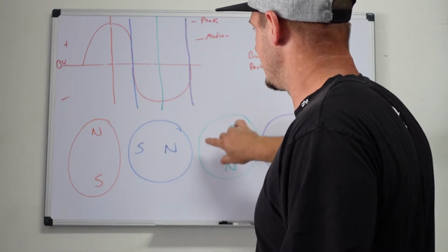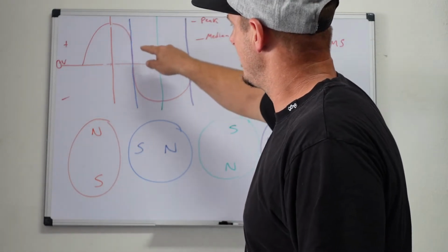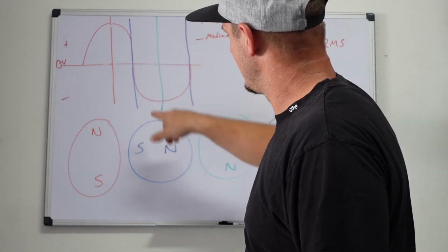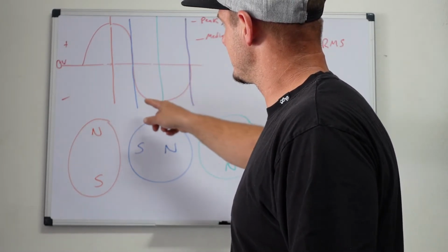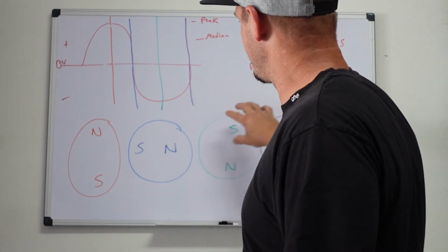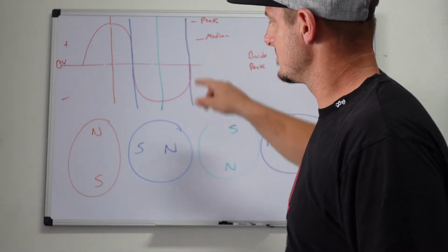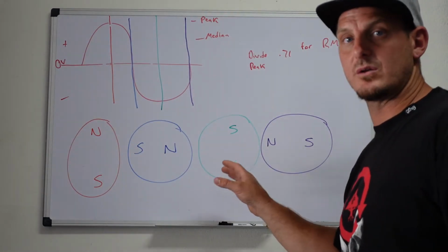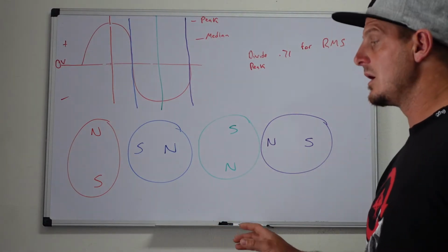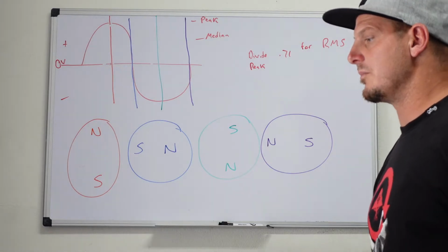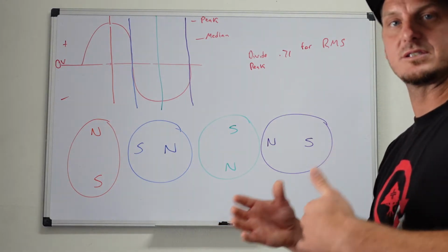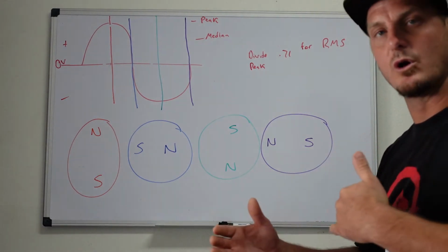As it then gets to the next quarter turn, it comes on the downside here. And then once it spins that other way, it goes to peak voltage here, and then from peak voltage it goes here as well. This is important because it's not only the way that a generator works, but it's the way that a motor works, but the rotor and the stator are just switched.